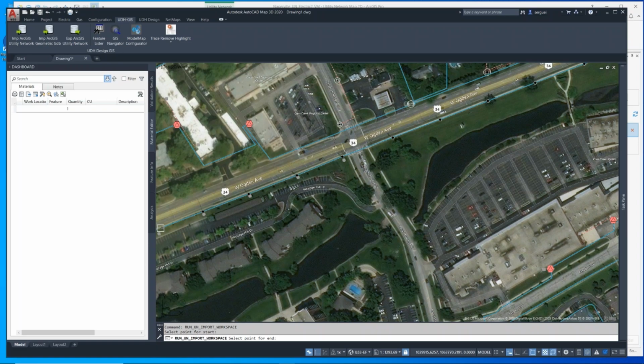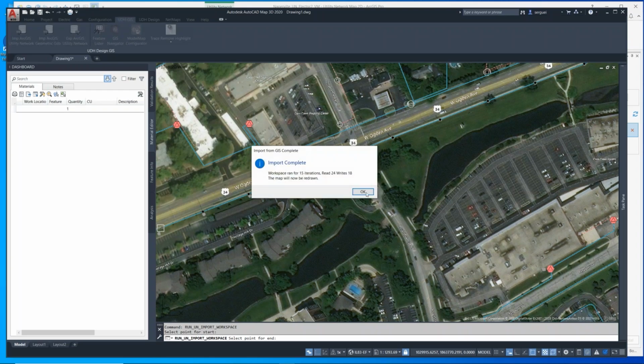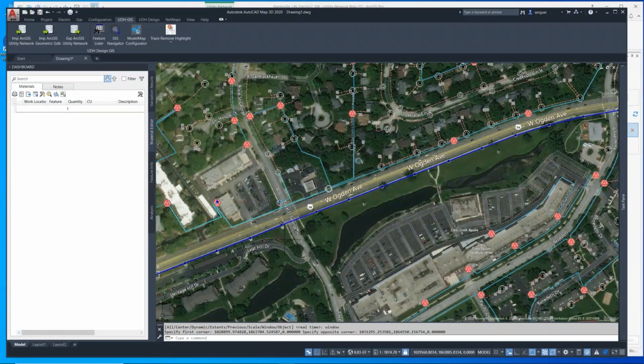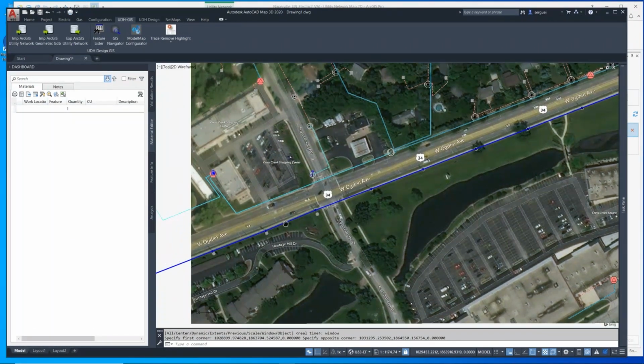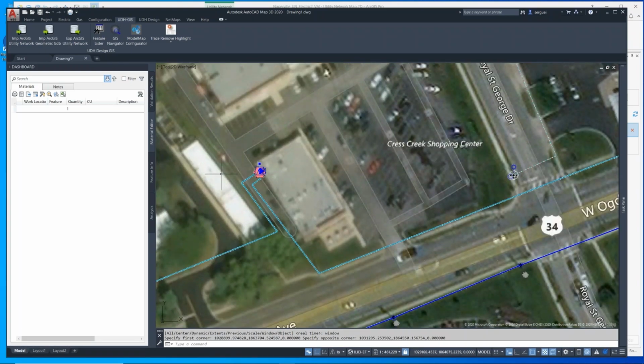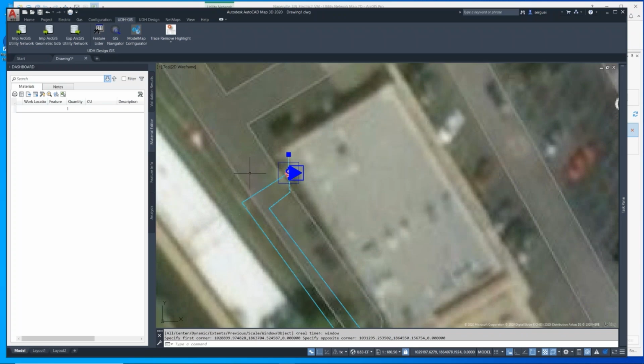So now the system uses feature services to get the selected subset of GIS features and transforms them into models that have been configured in AUD. And now I have those models available for me, created from GIS asset attributes as models in AUD, available for my design. So let's explore what's happened, and let's look at our pad mount transformer.